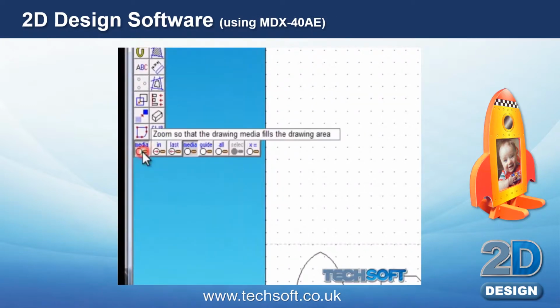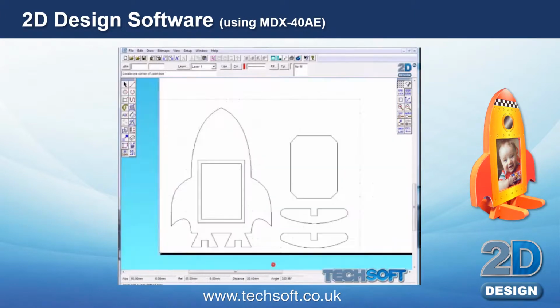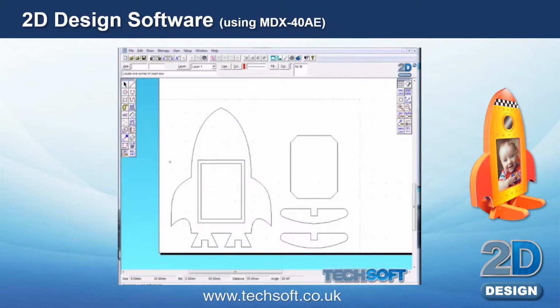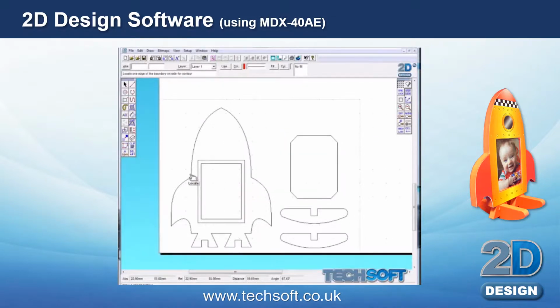We'll now zoom in. Due to the slot drill being used being 2 mm, we'll need to cut 1 mm away from the line. We're going to do this with a red line. We're going to go contour, 1 mm, okay, and go on the outside of each line that's going to be cut all the way through.